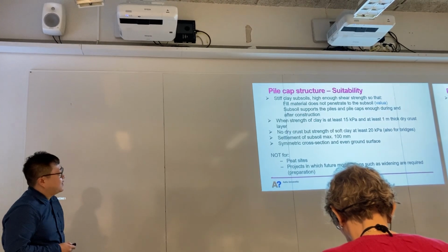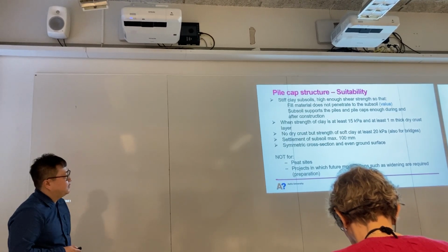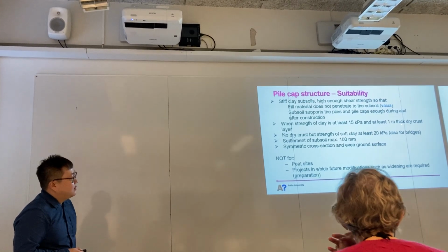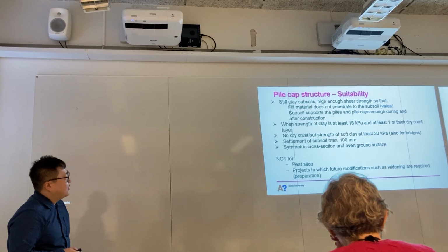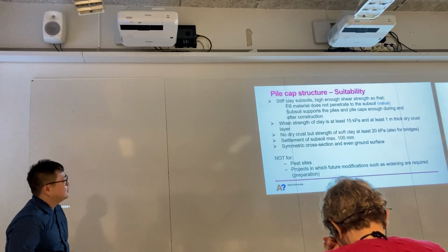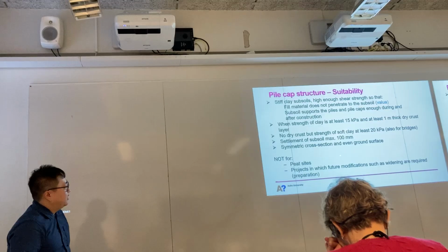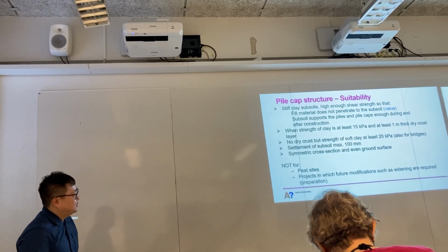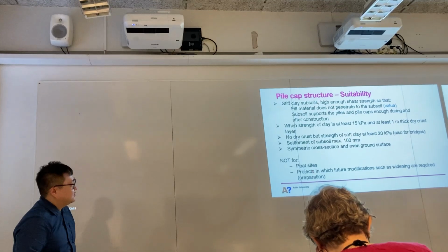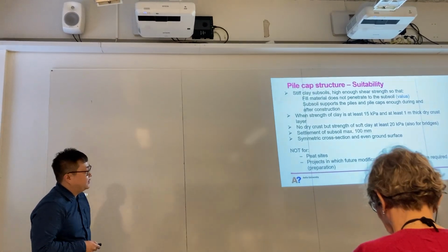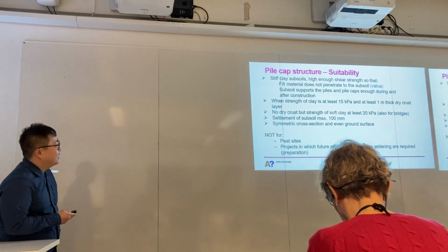Also, when the strength of the clay is at least 15 kilopascals and there is at least a 1 meter thick dry crust layer, we can choose the pile cap structures. Here we should be careful. The pile cap structure is not suitable for projects in which there will be some future modifications for the piles.